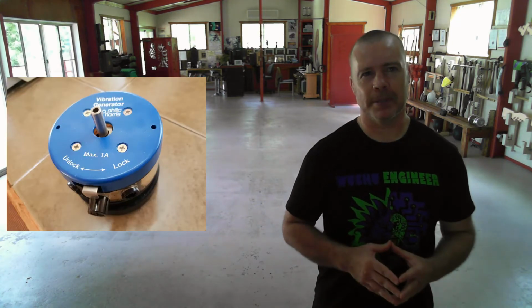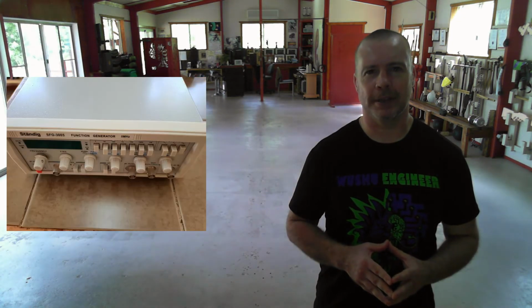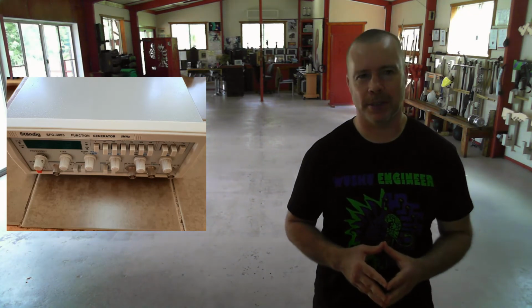Approximate sampling rates would not provide the necessary precision in this case for these tests, because my tactile response times are typically less than 100 milliseconds, requiring relatively high precision and resolution to show the pertinent details. So I set up a high precision laboratory vibration generator driven by a desktop frequency generator to produce a very accurate mechanical oscillating signal that could be used to individually verify both the belt sensor and the load cell and confirm their exact sampling rates.